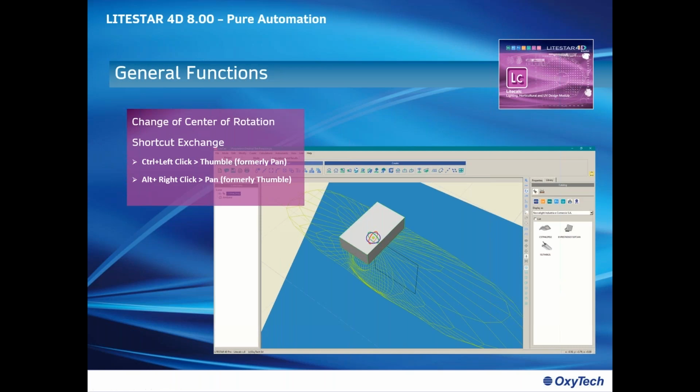This change was needed because now Control plus left click of the mouse can also be used to select objects. So, for example, if you have a panel at the top of a high mast where you have 40 different luminaires and you want to select some luminaires that you want to replace with another type, now it is possible to do that. Besides the list that you have on your left, it is possible to do that graphically, visualizing the panel of the high mast.